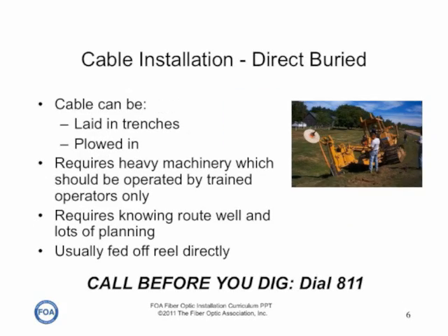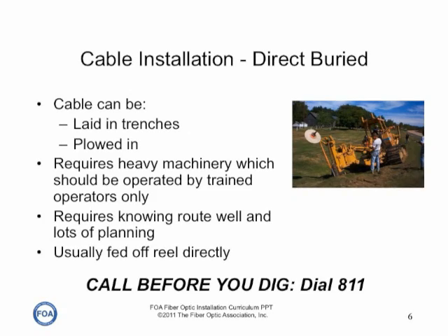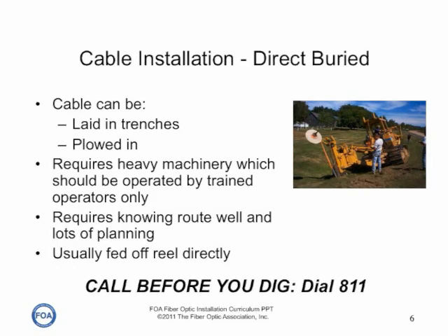Direct buried cables can be laid in trenches or plowed in using special heavy machinery. Of course, you always use armored cable for direct buried cable because it protects the cable from crushing and from rodent penetration. It's very important to know the route well and do lots of planning before you do direct buried